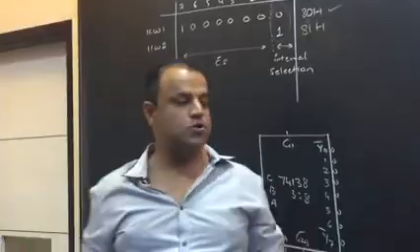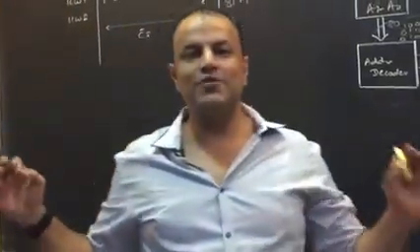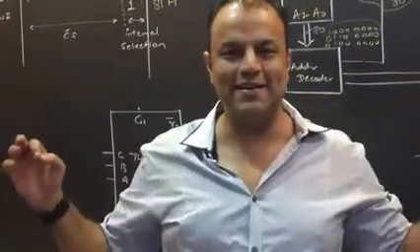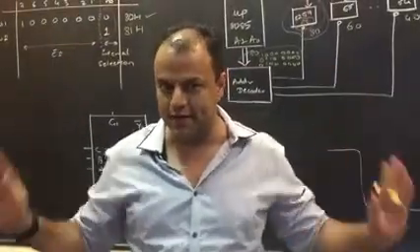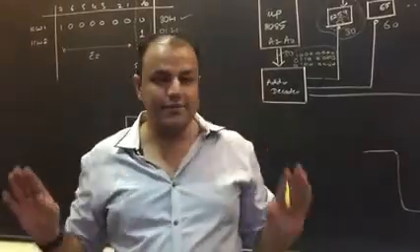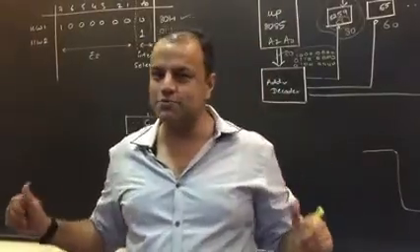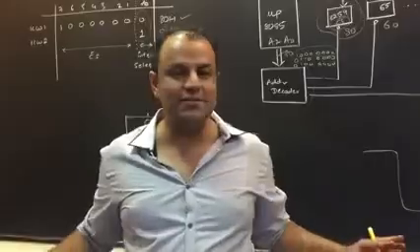Did you understand? So, for the last time, we are going to select this chip only when the address is 80 or 81. Are we clear? 80 or 81. Any address other than 80 or 81, this chip should not be selected. If it is selected, our sum is wrong.